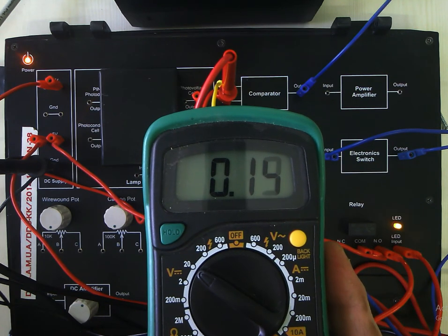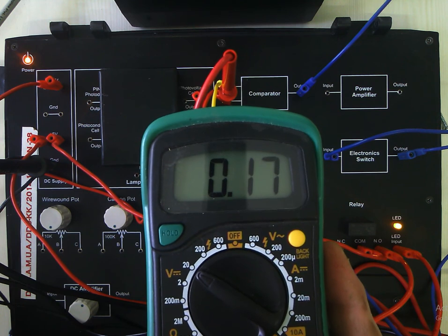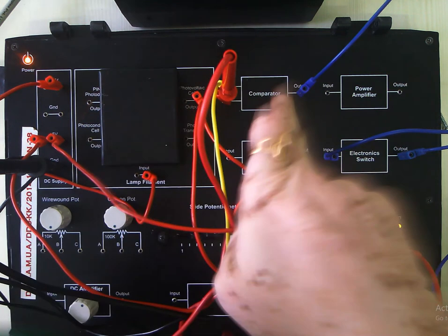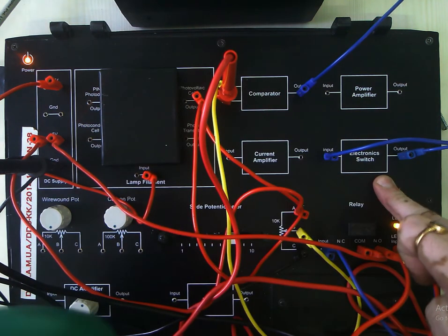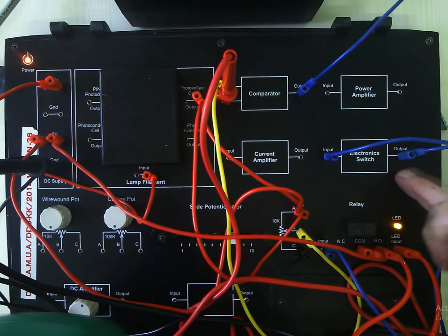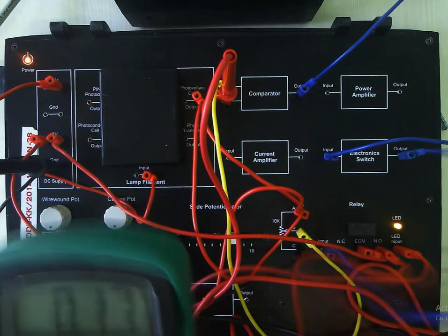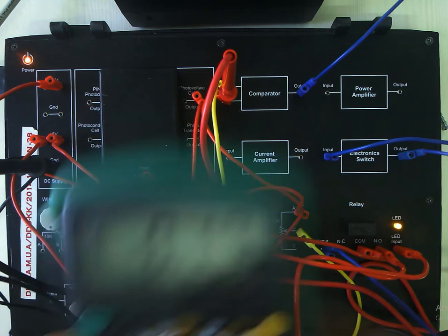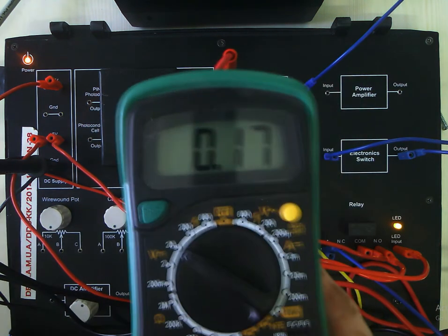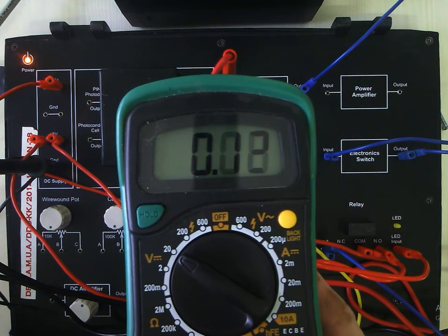Observe closely. Now you can see beyond 1.5 the LED is on, because the output of the comparator is now fed to an electronic switch. It is giving the output and that output is driving the relay. So you can find this output is connected to the relay. So again you can see, if I decrease the photo voltage,